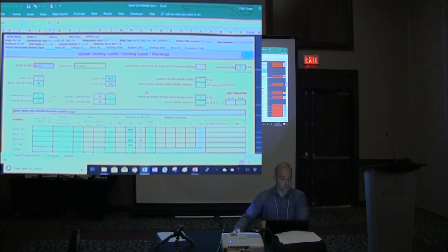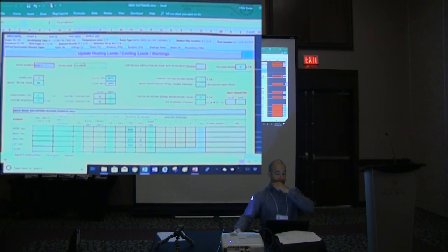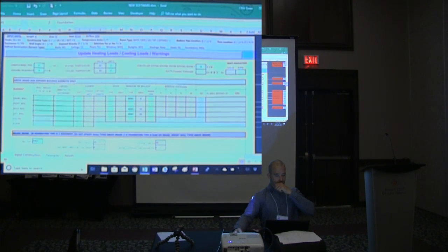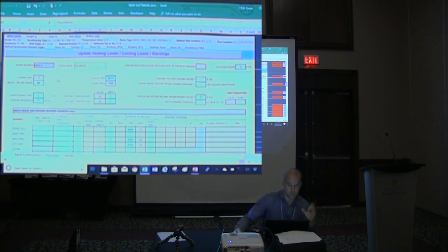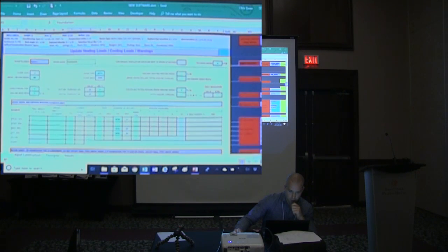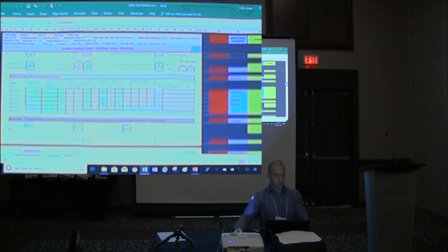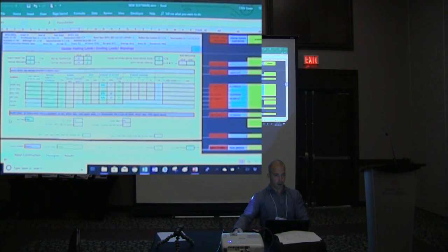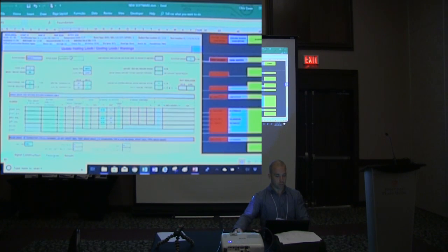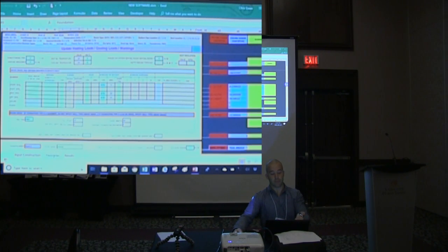Down here I've done the first room. It's a foundation. Remember, so this is, that's my bad. I kind of jumped the gun there. This is for above grade and exposed building elements, all of this. And then right here, this is for below grade elements. So we have a foundation room. We leave all this blank, for walls and everything. Obviously, windows are still an above grade element. And you just type in your foundation type, your wall height, depth below grade, length, and exposed perimeter.